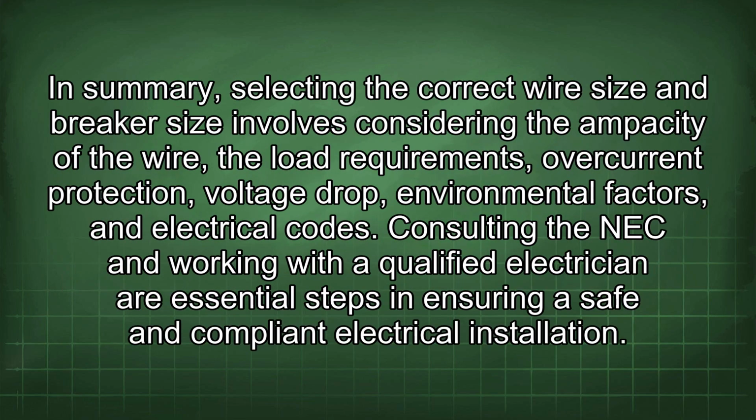In summary, selecting the correct wire size and breaker size involves considering the ampacity of the wire, the load requirements, overcurrent protection, voltage drop, environmental factors, and electrical codes.